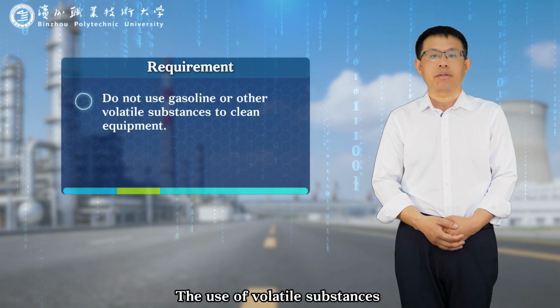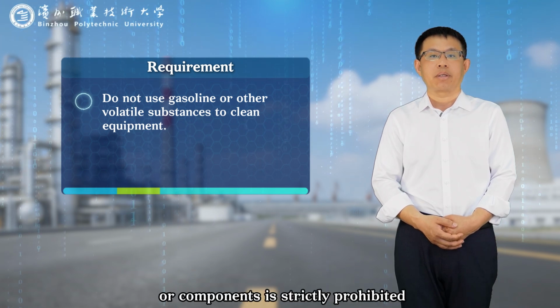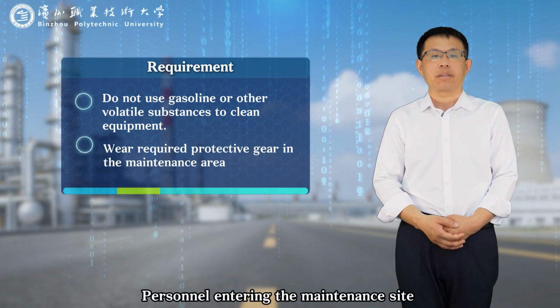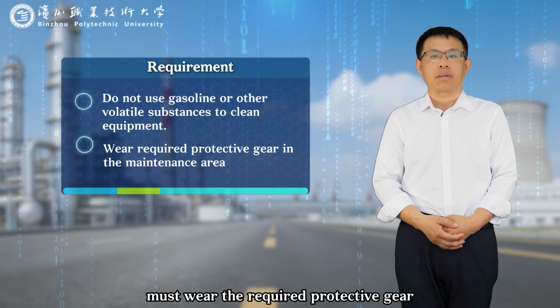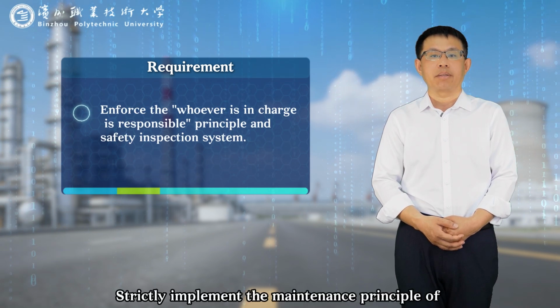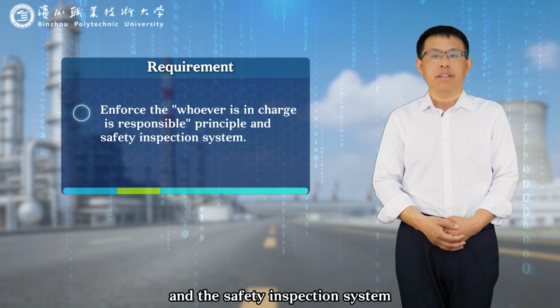Third, the use of volatile substances such as gasoline to clean equipment or components is strictly prohibited. Fourth, personnel entering the maintenance site must wear the required protective gear. Fifth, strictly implement the maintenance principle of whoever is in charge is responsible and the safety inspection system.